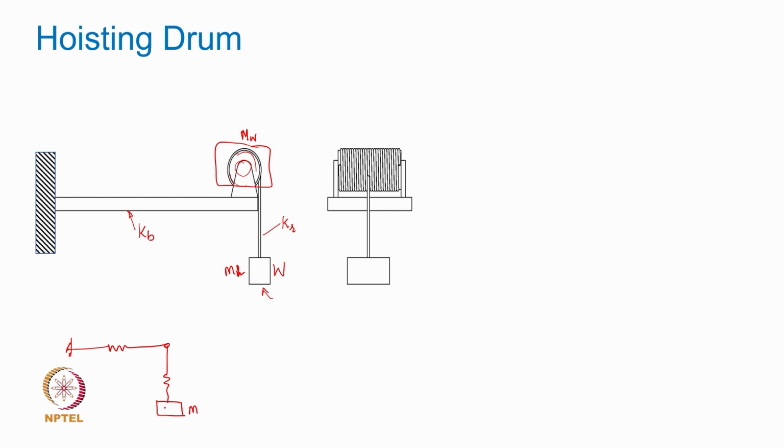And although they look orthogonal here, you can easily club them as a single equivalent spring, these springs being in series, you can finally get the entire system model like a simple single degree of freedom system. However, it all is going to be an approximation, because based on the numeric values of the winch mass and the weight being lifted, one can approximate in the modeling process. We can ignore the mass of the winch, but suppose this mass being lifted is comparable. Okay.